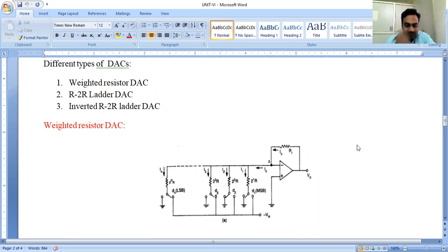Most of you are familiar with the terminals of the operational amplifier. It has 5 terminals, 2 input terminals: the negative terminal is the inverting terminal, and the positive terminal is the non-inverting terminal. We also have two biasing voltage terminals, which I haven't shown, and the output voltage terminal is V0. A negative feedback is provided in order to set the proper gain.